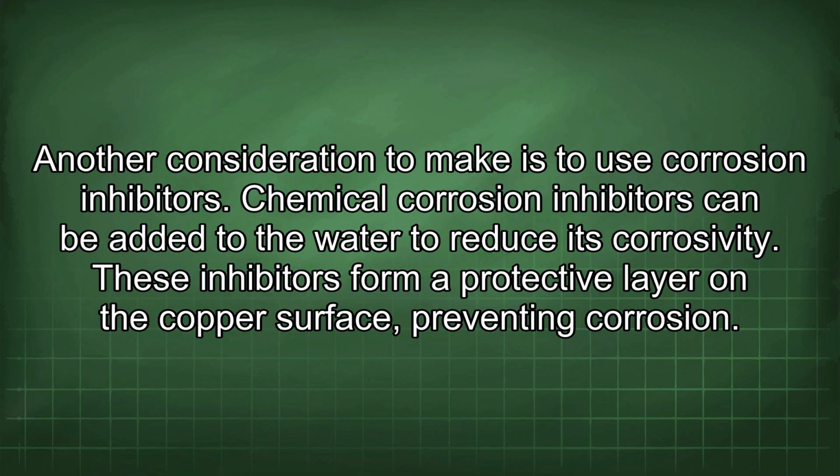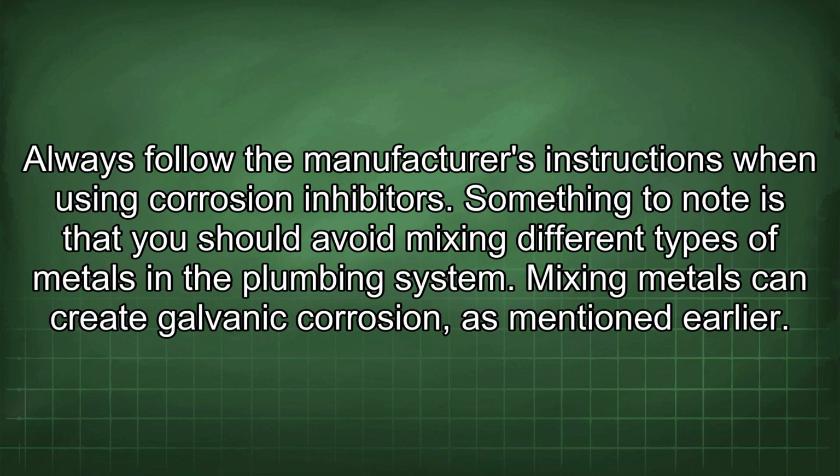Another consideration to make is to use corrosion inhibitors. Chemical corrosion inhibitors can be added to the water to reduce its corrosivity. These inhibitors form a protective layer on the copper surface, preventing corrosion. Always follow the manufacturer's instructions when using corrosion inhibitors.